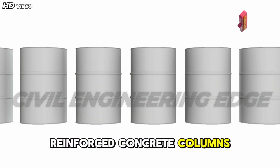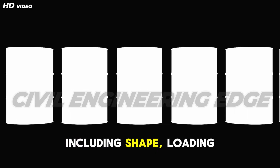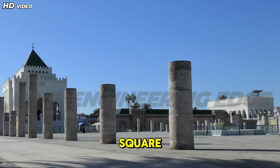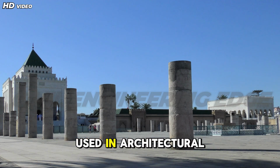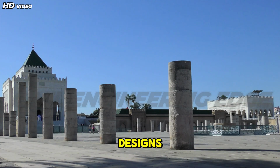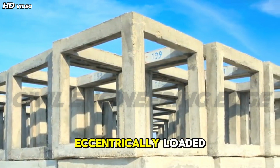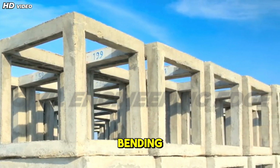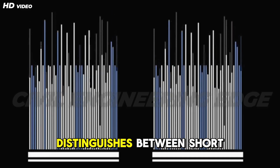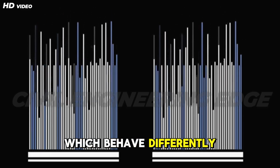Reinforced concrete columns are classified based on several criteria, including shape, loading condition, and slenderness. Common shapes include square, rectangular, circular, and special shapes used in architectural designs. Based on loading, columns may be axially loaded, eccentrically loaded, or subjected to combined axial load and bending. Slenderness classification distinguishes between short and long columns, which behave differently under load.